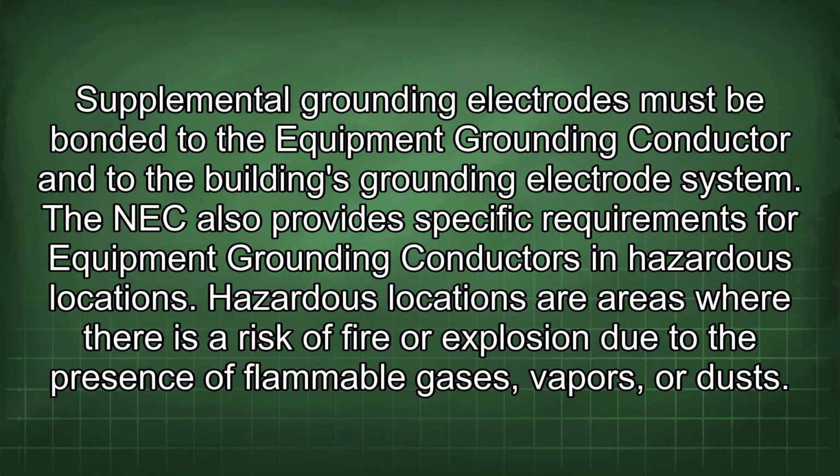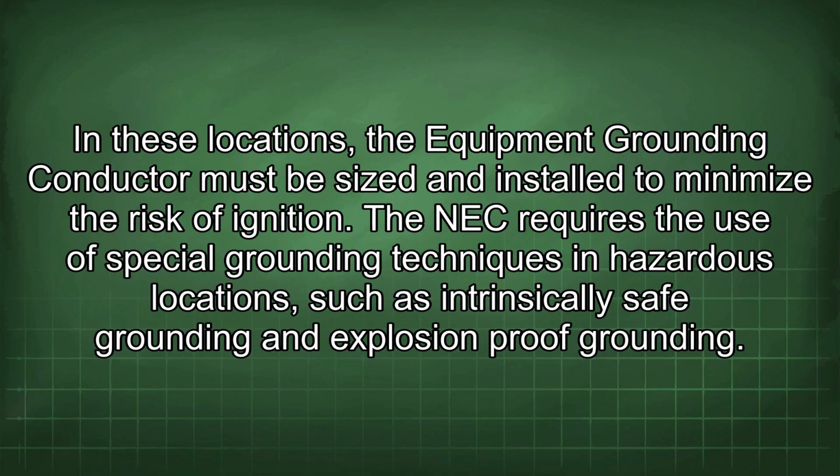system. The NEC also provides specific requirements for equipment grounding conductors in hazardous locations. Hazardous locations are areas where there is a risk of fire or explosion due to the presence of flammable gases, vapors, or dusts. In these locations, the equipment grounding conductor must be sized and installed to minimize the risk of ignition. The NEC requires the use of special grounding techniques in hazardous locations, such as intrinsically safe grounding and explosion-proof